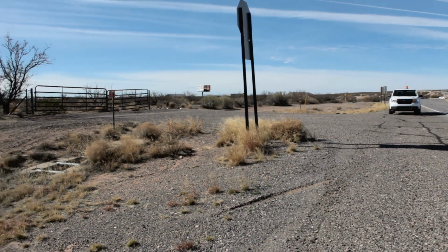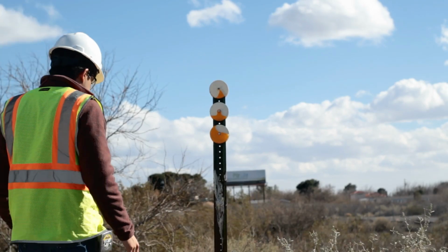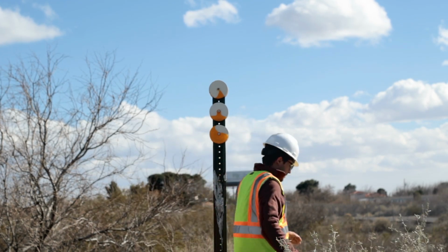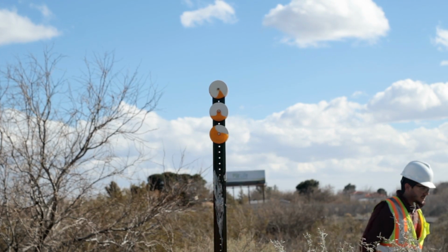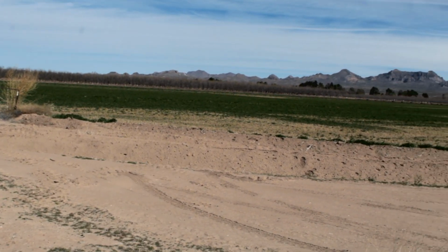Turnouts or driveways. This location is used for culverts crossing US and state roads, private drives, or commercial sites. As we mentioned in another video, a triple orange reflector T-post can be found, but sometimes there is no culvert. In those cases, geolocate the post, mark the location as triple orange reflector, and take a picture of the post and include some background information. Other location options are irrigation, when the culvert is used to water crops, or other in cases where the location doesn't fit in any of the previous options.